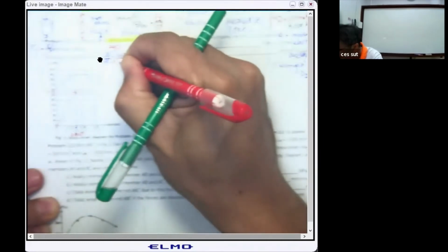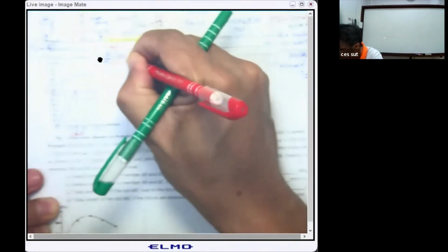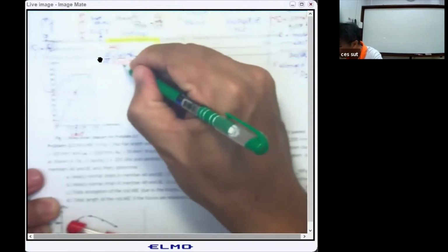0.0015. So by doing this, you have the modulus of elasticity of 260 divided by 0.0015. You can change this to meter per meter, and this is going to be in megapascal. So you may say this is 260 divided by 1.5.